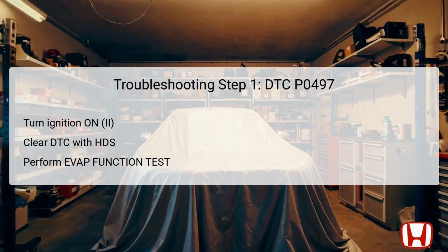If the test results in a pass, the vehicle may have an intermittent issue, prompting a detailed check of critical connections such as the FTP sensor and the ECM. If the test fails, further inspection is necessary, leading to the next troubleshooting steps.